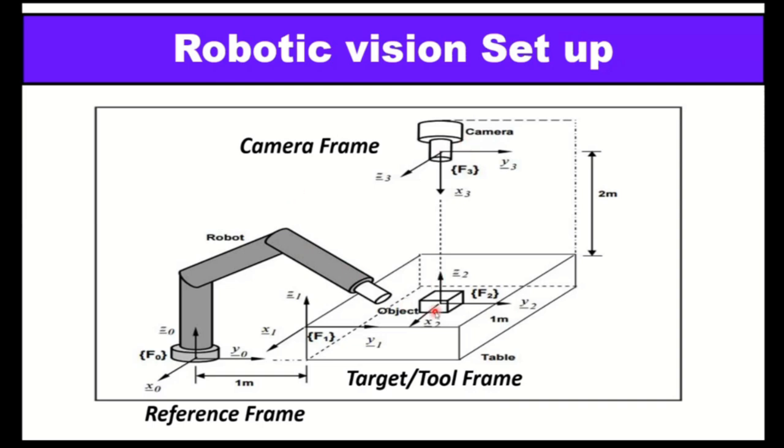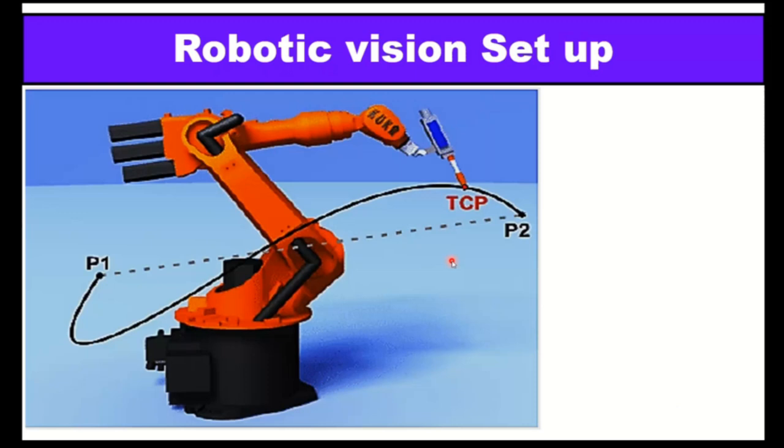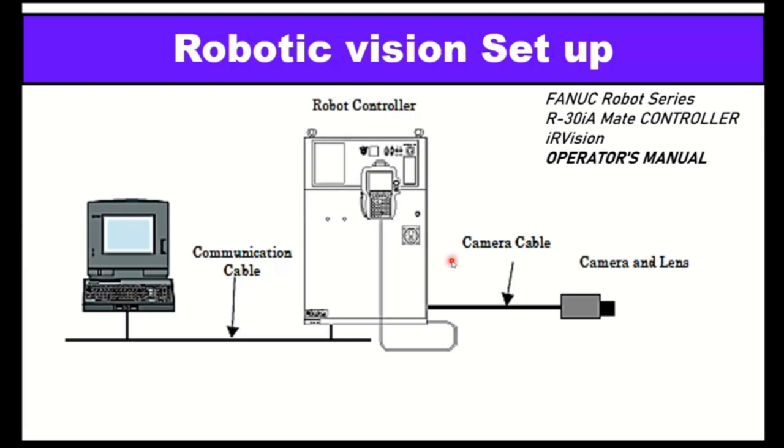Now this will go and move to the place workspace. So at that time, tool and object all enter the camera frame of the place operation. Again it has to come back, and again it has to realign all three things. This is how a real operation goes. This is what is said as frame calibration. Now the robot has a communication cable and controller. This is another type of robot that we are showing, and there is a camera every time.